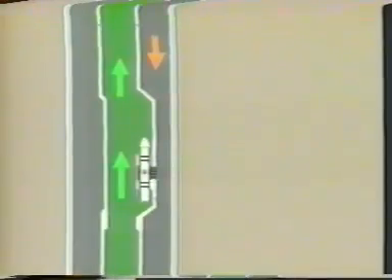Another commonly used device installed using wireline is the gas lift valve. Modern gas lift installations are designed to allow gas lift valves to be installed and removed at various locations within the tubing string to allow the well to be unloaded or produced using gas lift. The side pocket mandrel is used to hold the valves and is run as a part of the tubing string. It is usually full tubing bore through the bore of the mandrel and incorporates in the design of the mandrel an offset side pocket. This side pocket has ports which provide for communication between the tubing and the casing.